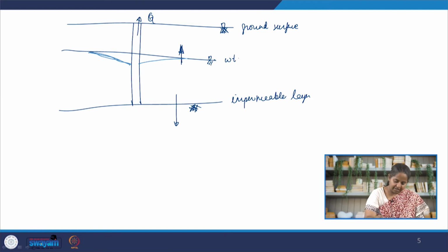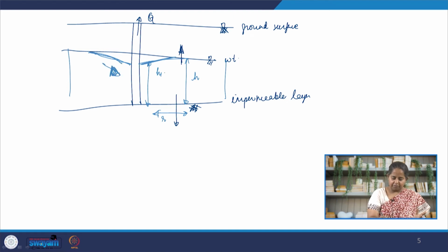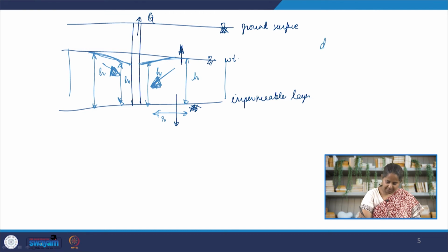So now let's say we have height h here and we have height h1 here, and the distance between them is r. The overall hydraulic gradient is not as important as this local hydraulic gradient, because this is driving the flow of the water towards the pump, right? The water table has fallen in the neighborhood of the pump, so the water is rushing towards the pump. So we are going to look at the gradient here. So let's say this is H. Here we have H1. So now we know what dH by dr is. Again, subtraction of these, H minus H1, divided by r.